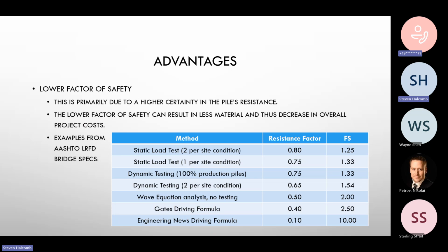So, you always want to leave a little bit of an insurance policy, and certainly we've gone where we're just going to plan on a restrike, or we're going to plan on 100% production because we know we're going to get it. Like we planned on restrikes at that 75 to 90 project because we knew we were going to get a lot of setup on those piles. So we put it in spec to say 24-hour restrikes. So I like this. So, any questions?